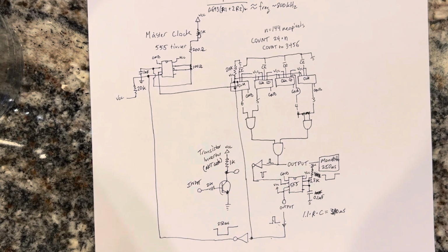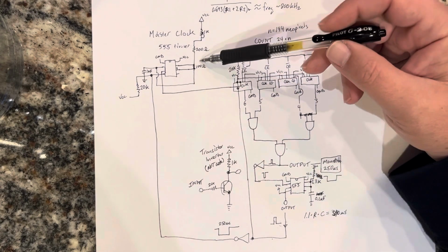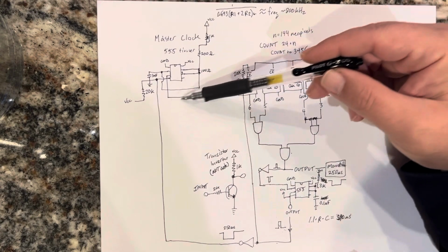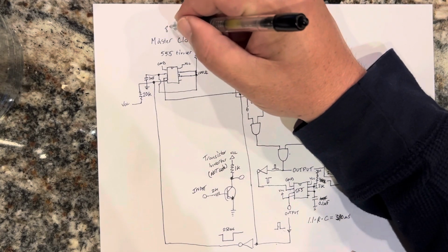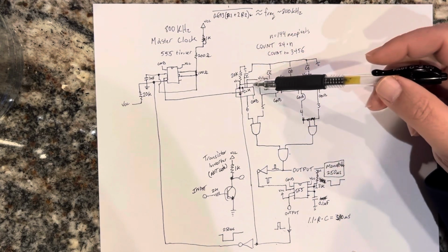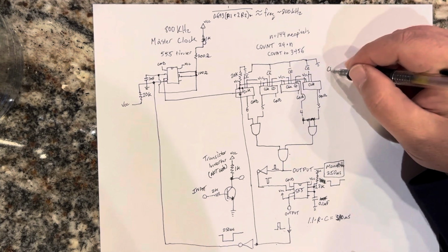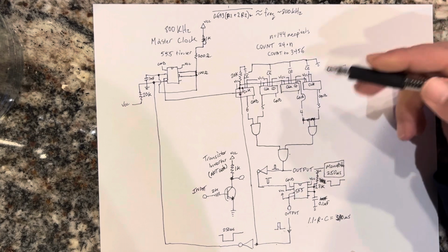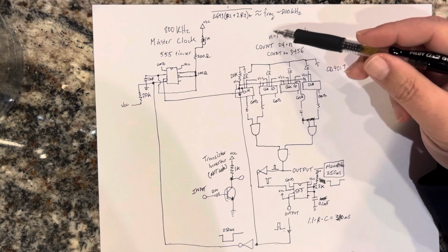In the previous video, I talked about the first part of the neopixel circuit and the most important part, which is the master clock. And so here's the schematic of how the master clock is hooked up. The master clock is an 800 kilohertz signal, and that is going to a bunch of counters. These are CD4017 counters that count up to the total number of bits in all the neopixels.